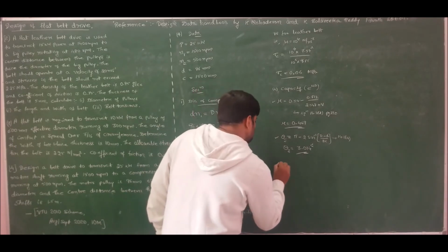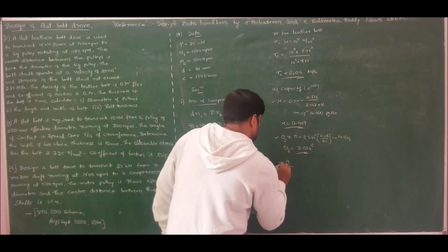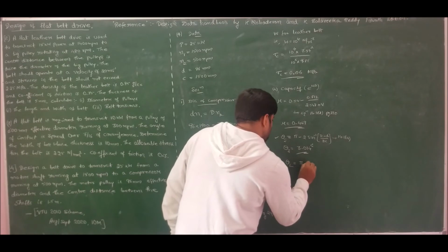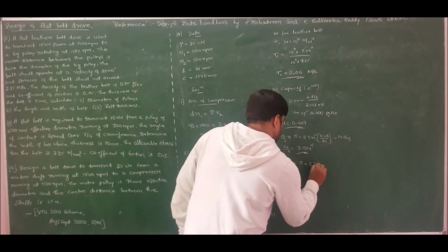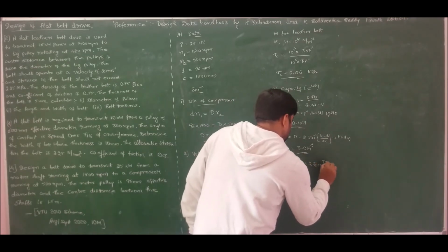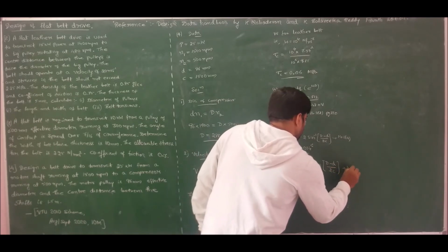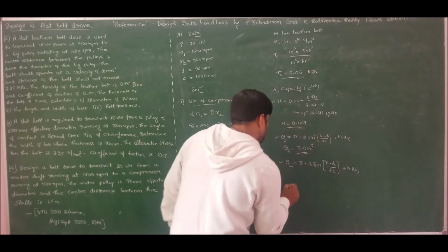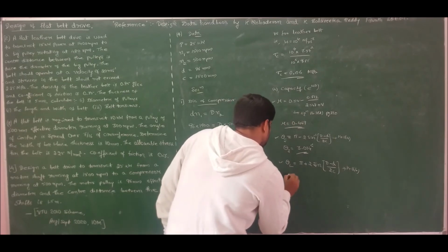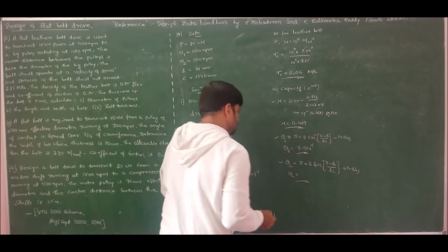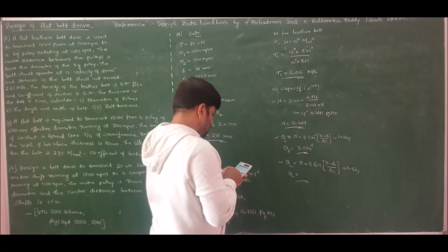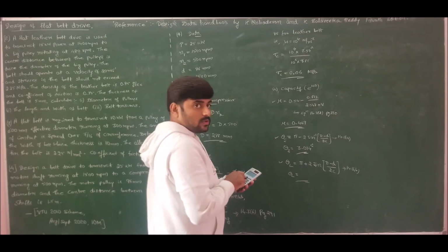3.014 radians, whereas theta larger pulley is given by pi plus 2 times sin inverse of D minus d by 2c. This is equation 14.1b. So we get the value of theta l as, just change the sign to plus. Make a note, your calculator should be in radian mode.